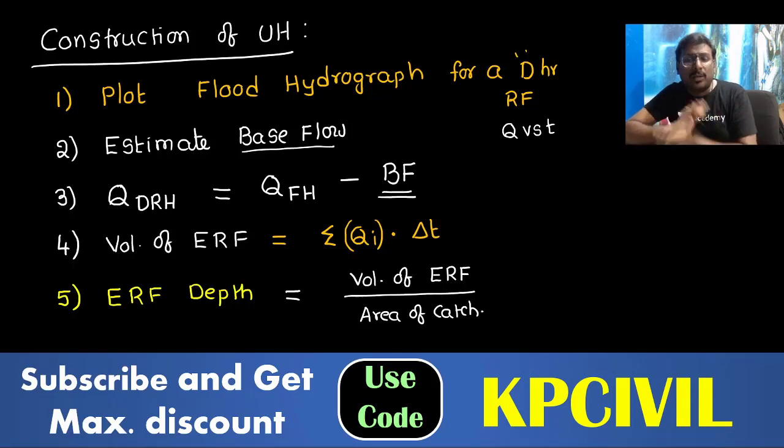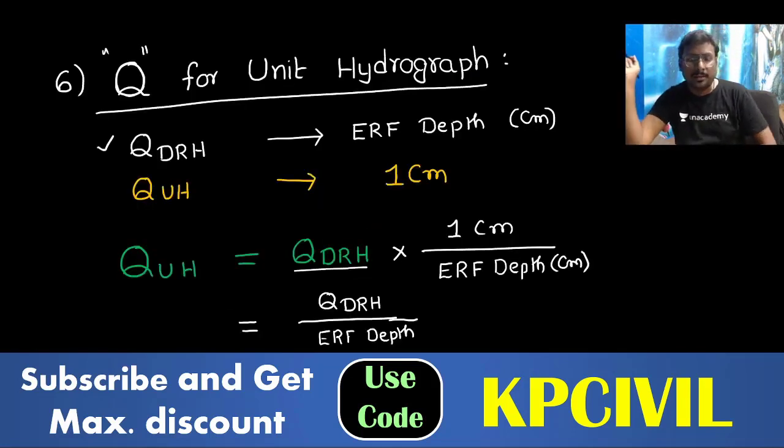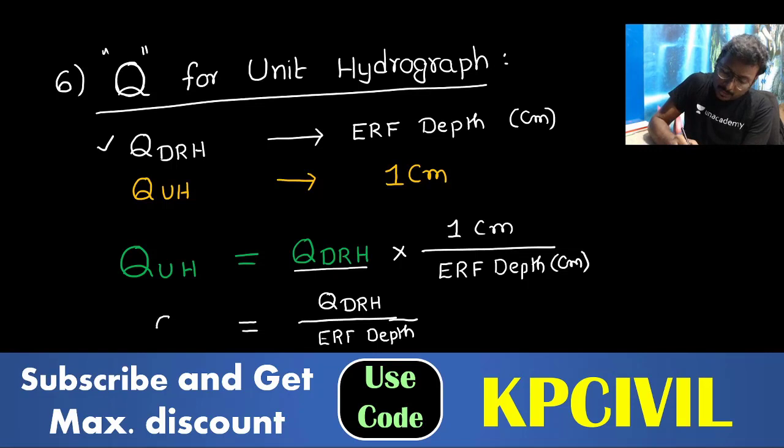Then volume of effective rainfall is the sum of direct runoff ordinates into delta T. Obtained volume by area of catchment gives effective rainfall depth. Then unit hydrograph discharge, one simple formula: QUH is equal to QDRH by effective rainfall depth.